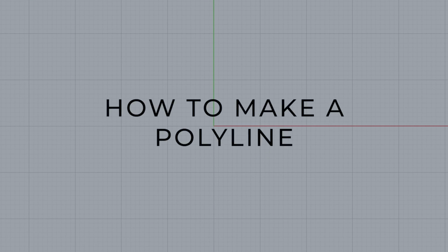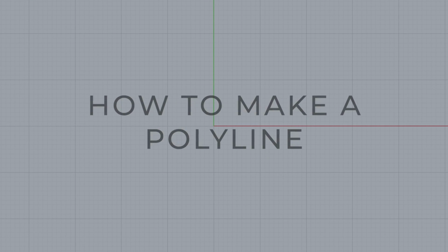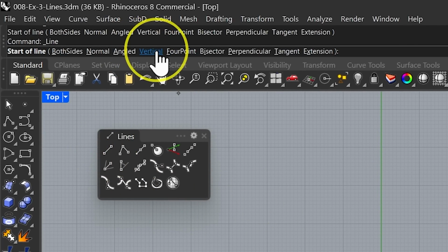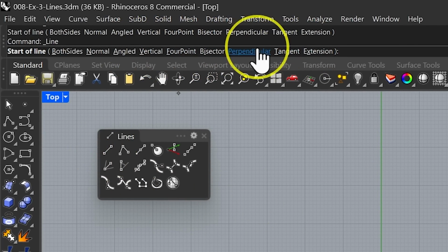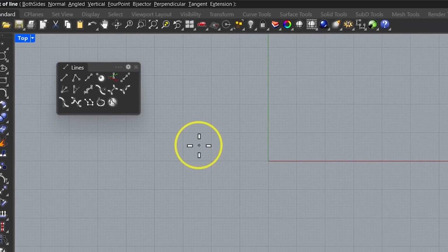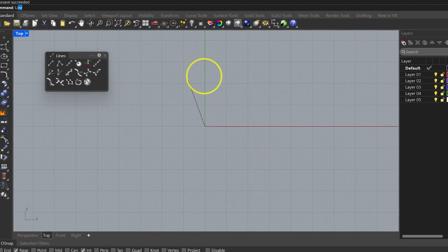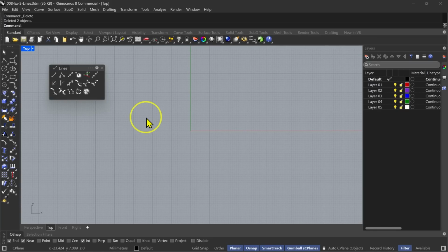Next, let's understand how we can make continuous lines in Rhino, or we can also say polyline. Remaining options in the single line command I will cover later with suitable examples and exercises. So I was talking about single line. There is a limitation in single line. As you start making the line and finish it, as shown on your screen, you have to restart the line command to make another line adjacent from the same one or connected to the same one. So for that case, we use Polyline tool. Let me show you a small demo on how Polyline tool works.